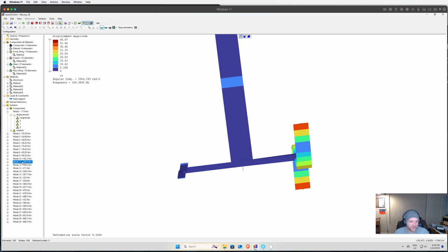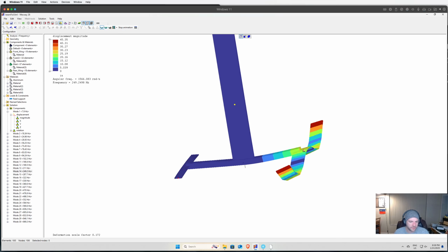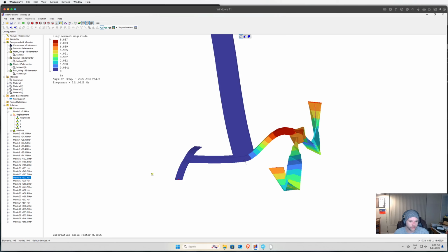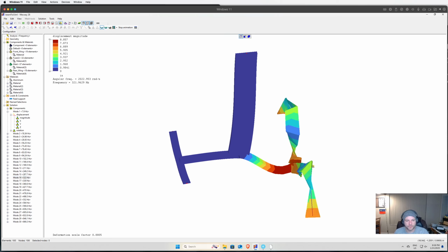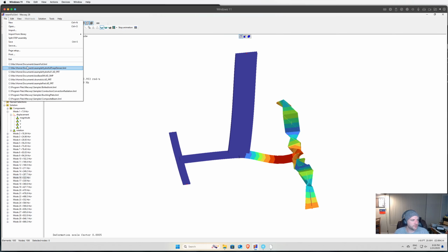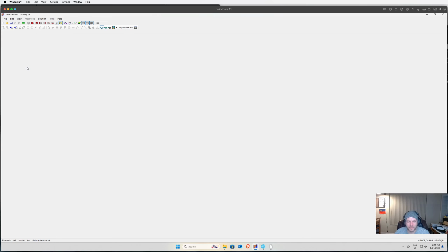And it also happens with, maybe not that one, just rear wing effect. I think it was around mode 15. Yeah, that's not quite what I was thinking about, where you get a torsional mode. Okay, this one. This looks really ugly because there's a twisting effect going on with this wing, and I think you actually see it better with the actual mesh of the TETs, because this model is pure beam, so it looks kind of silly. It doesn't really animate that well.